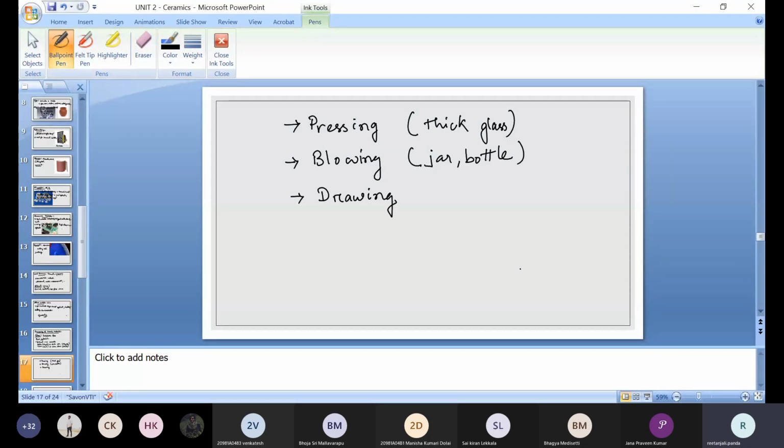Similarly here also we are heating the glass to a higher temperature, then we are putting a tensile force on that one, so that it is getting elongated and elongated and giving us the wire like structure or tube like structure or rod like structure. Okay, so here what we will be getting? Rod, tube, wires, like that. Okay, these are the three different type of manufacturing procedure for the glass.